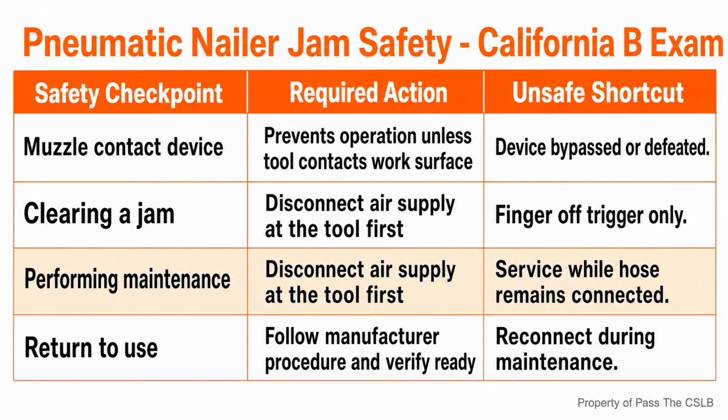A shear panel is a chain of real connections. The panel edge must have enough material around the nail. The nail must be seated without crushing the face. The nail must enter real framing. The framing must be wide and sound enough for the specified pattern. The edge must be supported. When those conditions line up, the fastening can do the job assigned to it.